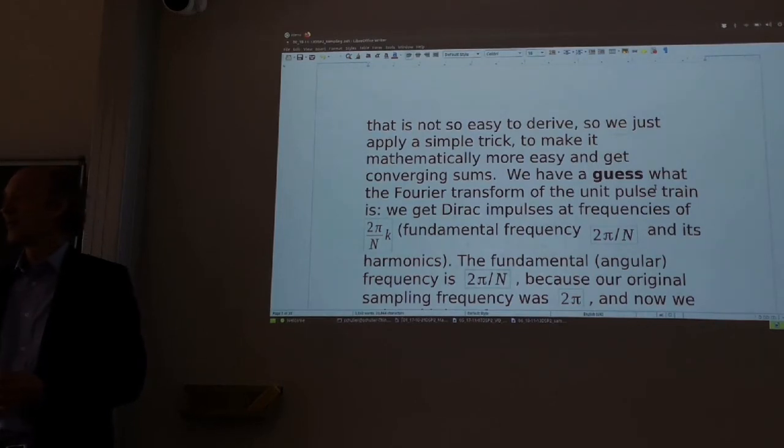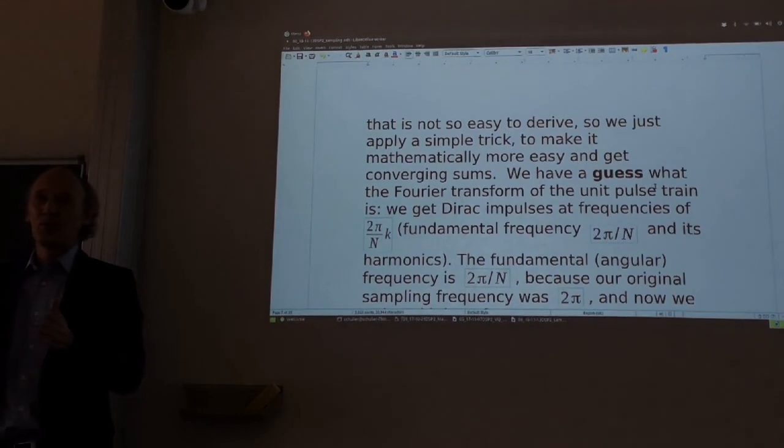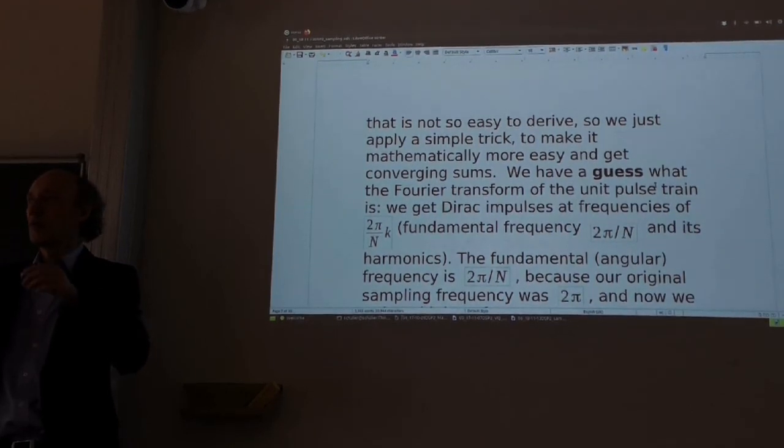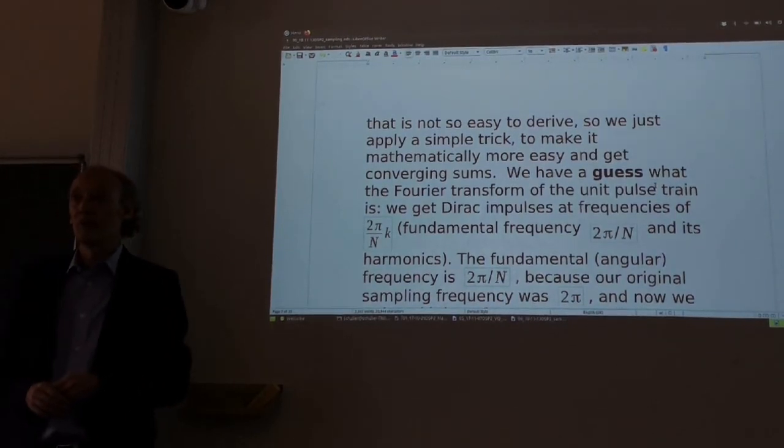Yes, the average. Exactly. If you have, for instance, a signal from a microphone, you just compute the average, and if all the plus and minus cancel out, then you have no DC. But if you have DC on it, then you will see that the average is non-zero, meaning some fixed voltage is on your signal. So DC is computed by computing the average.